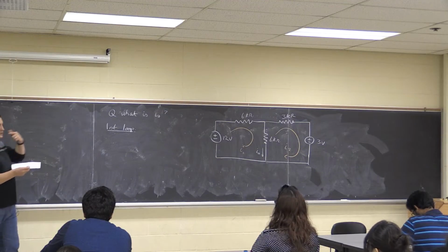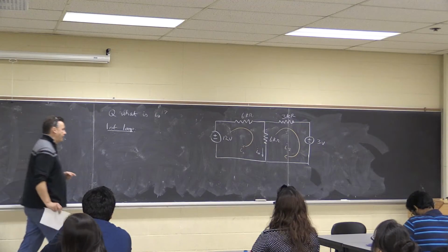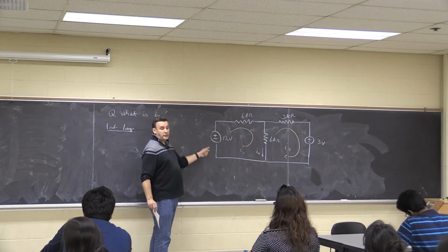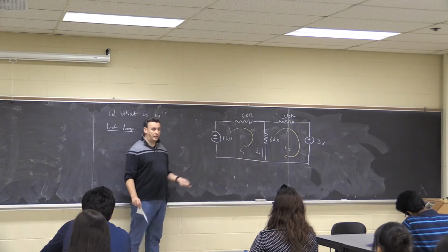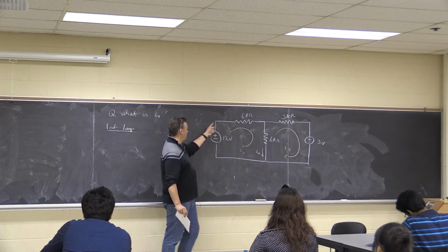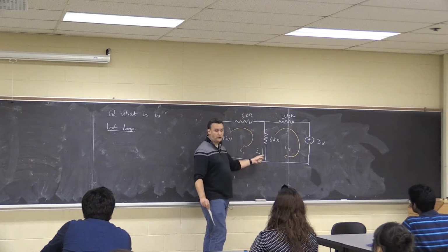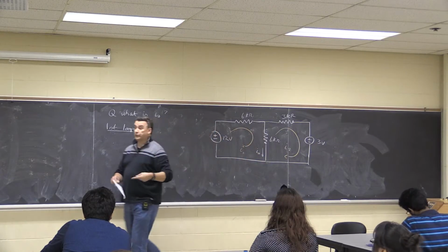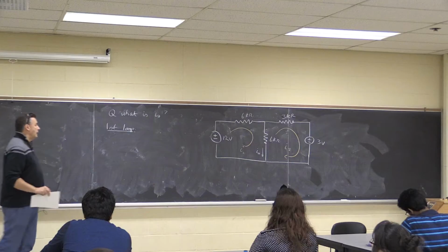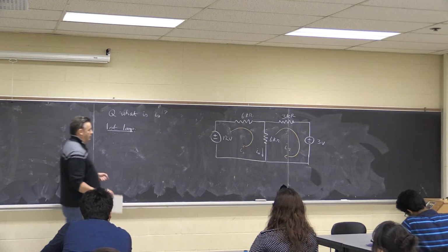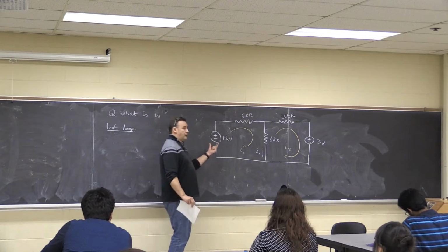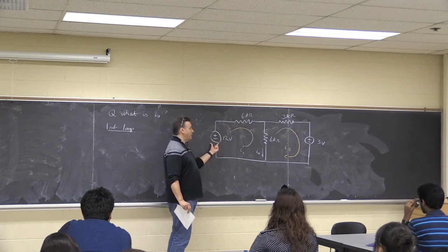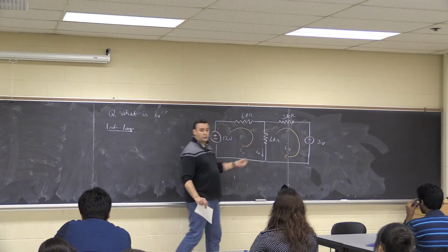So as we go through a resistor, we've got a voltage drop. As we go through this source, we've got a voltage increase. So I know this voltage increase must equal this voltage drop and this voltage drop. So if I walk around that first loop, I know that happens. Now I could have, and we talked about this last time, I could put on one side of the equations the voltage increases, and I could put on the voltage drops at the other side.